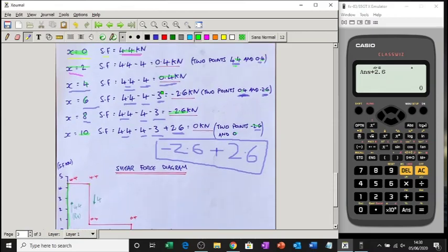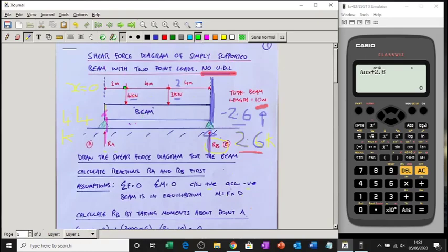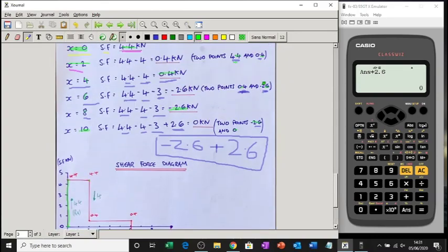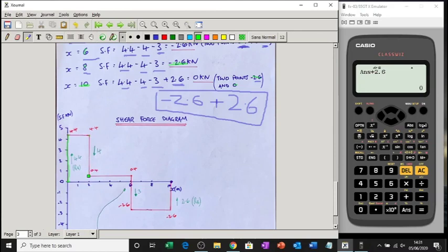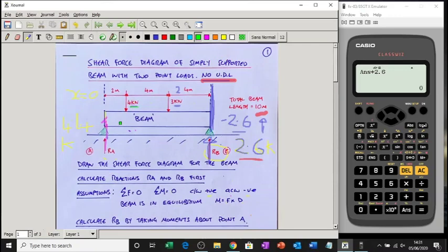But don't forget, I've got 2 points, so now this is where my 4 kilonewtons kicks in. So I come down to 0.4, bang, down, across comes the line, and down it comes. That's the point load. So it comes up 4.4, across, and then when the 4 kicks in, it comes down. Don't go from there to there. You need to come across and straight down. There's 2 points.